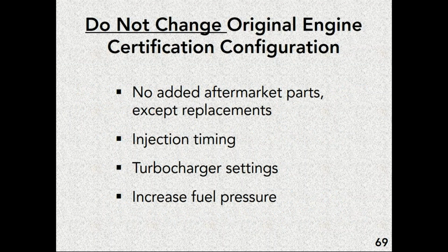Not changing the engine's original certification configuration. What that means, and this goes back to the aftermarket parts discussion that I had earlier, is you really don't want to be adding components that are going to change the emission parameters, because that's going to change how the filtration system functions. It's going to change how it reacts and how it's able to keep up or not keep up with the particulate matter being produced by the engine.